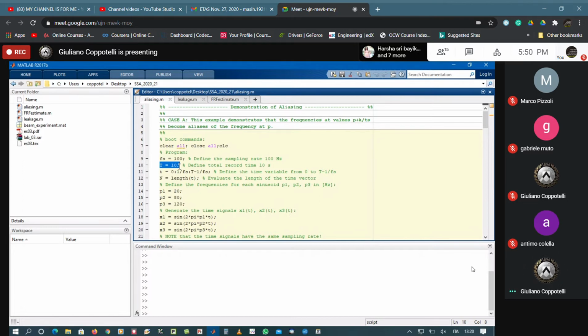And then the first time variable that I'm going to define here is the time at which I have knowledge about my signal. This small t here is a variable that goes from 0 up to the total overall time with an increment equal to the sampling time, that is just equal to 1 over the sampling frequency. In order to see that, I suggest you go back, I think 1 week in time, to see the general relations between sampling time, sampling frequency, observation time, and frequency resolution, so that you have all the things together in one shot, but we already dealt with that.